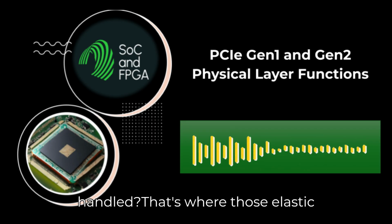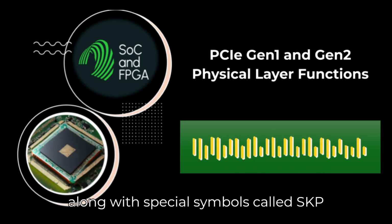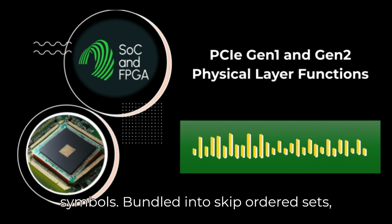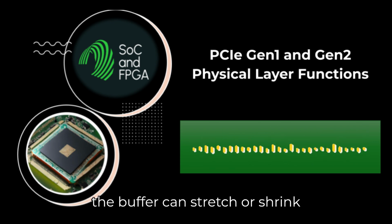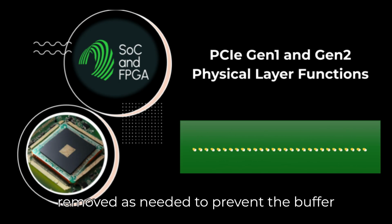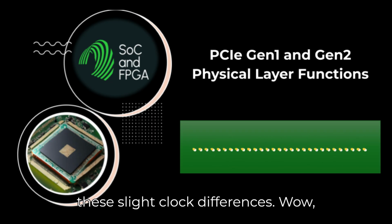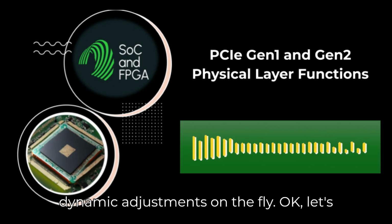How is that handled? That's where those elastic buffers on the receive side come in, along with special symbols called SKP symbols, bundled into skip ordered sets. The buffer can stretch or shrink slightly, and SKP symbols can be added or removed as needed to prevent the buffer from overflowing or running empty due to these slight clock differences. Wow, dynamic adjustments on the fly.